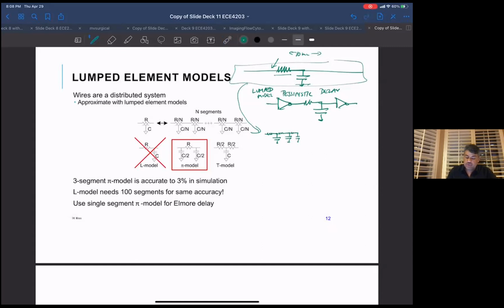It's basically a distribution of resistance and capacitance evenly all across the line. I'm drawing it like these little things, but they're really infinitesimally small resistance and capacitance pairs all across the line. And that's a more realistic model, but the simplest model is just the lumped.